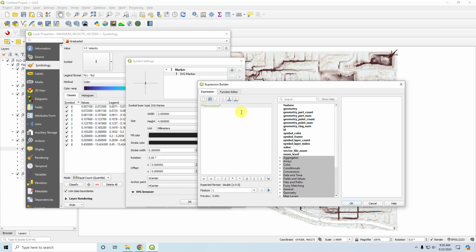So you can modify that and you can set the velocity to like say times 2 or maybe times 0.5 or something like that. So you have some control over that. If it was final velocities, I might make it times 2 or times 10. But if it's regular velocities or they're high velocities, I might use times 0.5. In this case, you can just leave them as is because this urban project has pretty decent velocity.